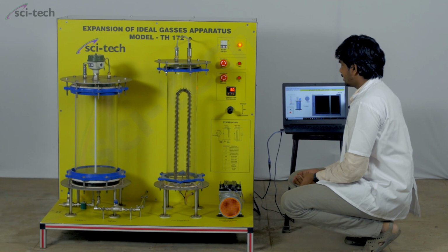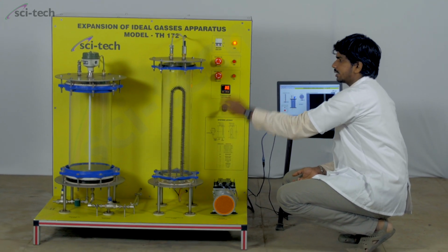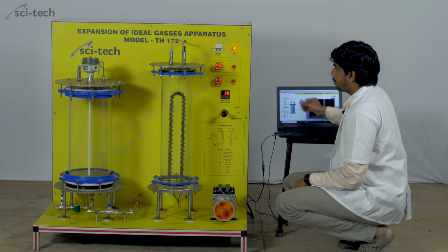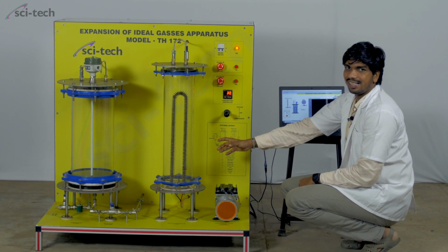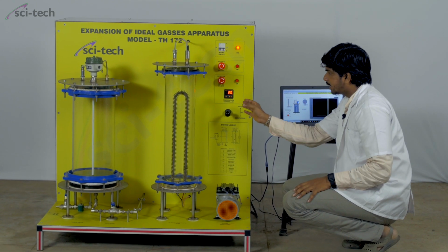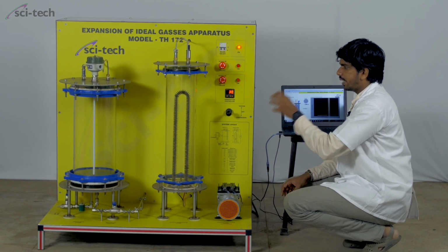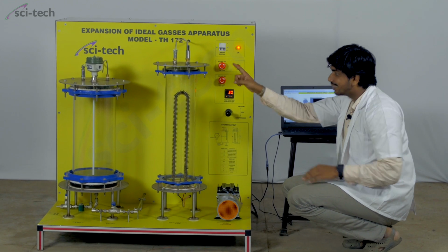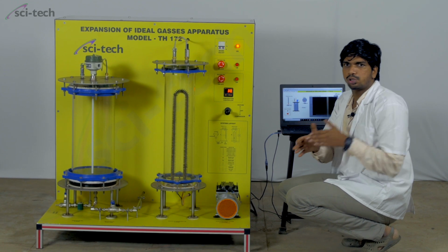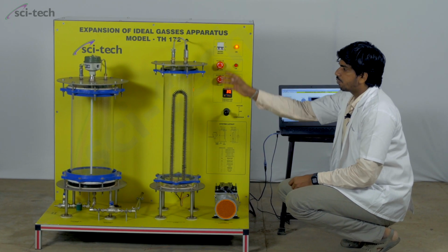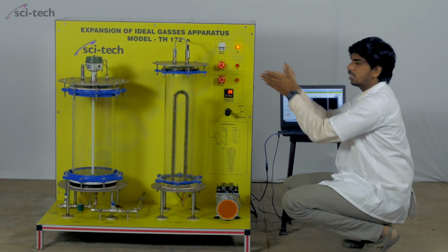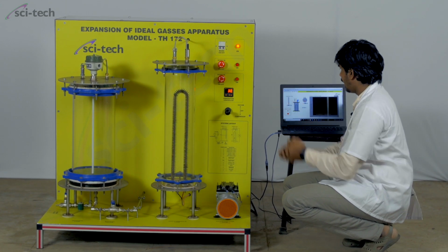Currently, as you can see, the temperature inside this glass tank is around 31.3 degrees Celsius and the pressure of the air inside the glass tank is around 0.0 bar. It means at 30 degrees Celsius ambient, our pressure is 0.0 bar inside this tank, not in the environment. In our environment it is around 1.013 bar, but we have already performed so many experiments inside this. So we have set it at around 31 degrees Celsius and 0 bar pressure.